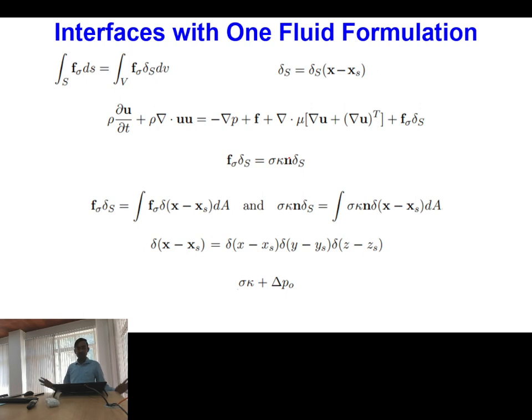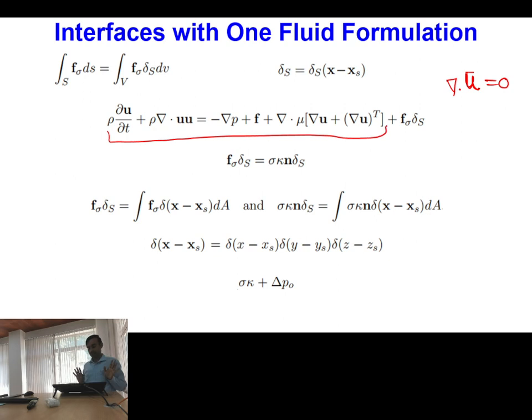The continuity equation for incompressible flow simply becomes divergence of velocity vector equal to 0, and in the momentum equation, the first term is the temporal term, then the convective term, pressure term, body force term, and viscous term. Up to this point we know this for single phase flow.